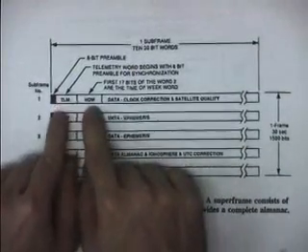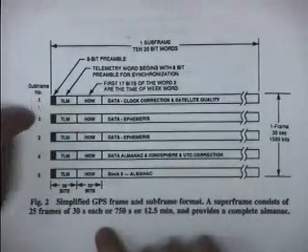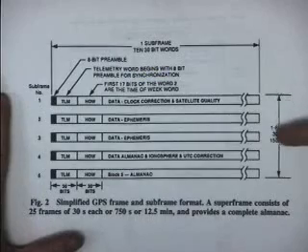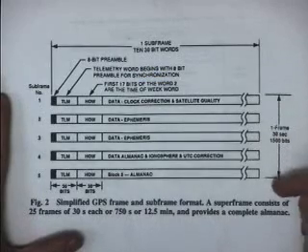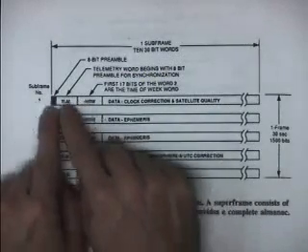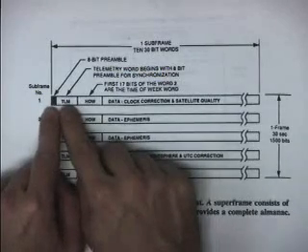So for example, there are these 5 subframes, and it takes about 30 seconds to do these 5 subframes. Each subframe lasts about 6 seconds. That means it's got about 300 bits in it. And it's got a little preamble so you can synchronize with it.